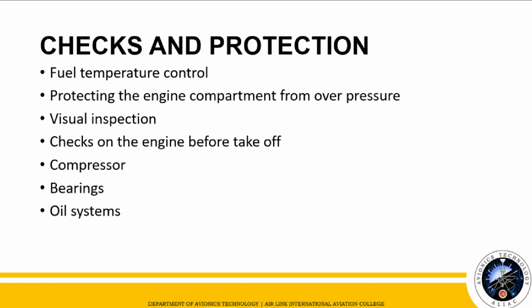A valve in the filter unit bypasses unfiltered fuel when this occurs. Fuel heaters are used to warm the fuel so that ice does not form. These heat exchanger units also heat the fuel sufficiently to melt any ice that has already formed.